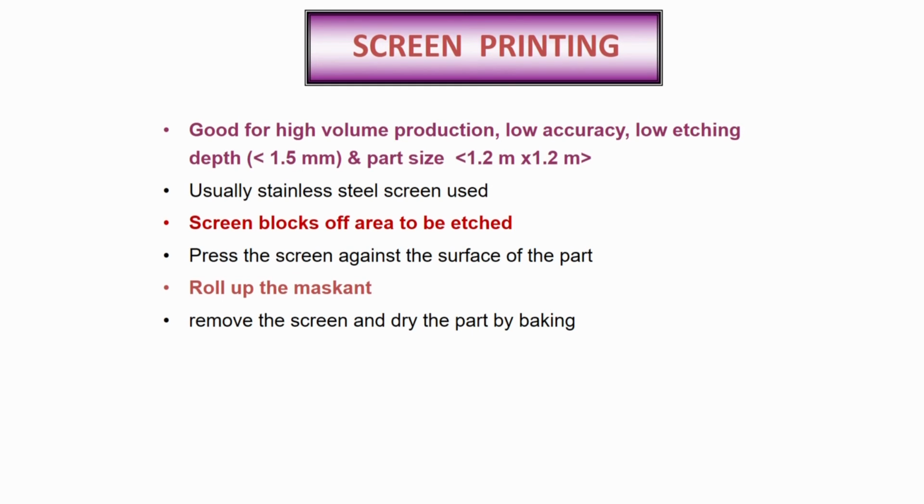And this maskant is filled in where there are gaps in the screen, and the rest of the portion will be opened for machining. So remove the screen, and after that dry the part by a baking operation.